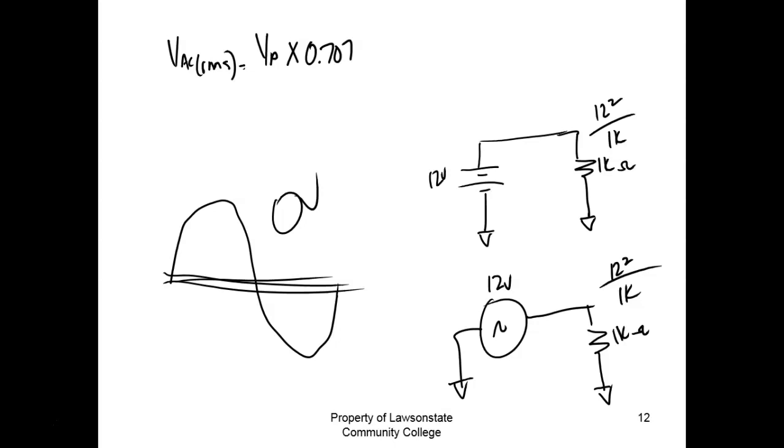You understand? So if we square a minus number, it becomes a positive. So that means, okay, if I square all these numbers around that sine wave, I'm going to come up with a positive number, right? You understand? And then I add them together, and then what I'm going to do is come up with an average, which we call a mean, but now it's a lot higher. So we squared them to start off with, so what are we going to do at the very end? We're going to take the square root, and that's the way these meters work.